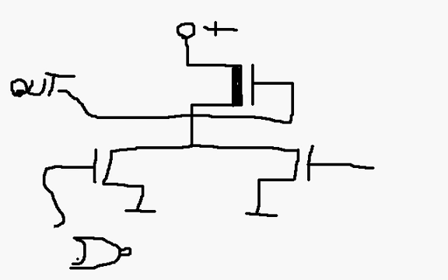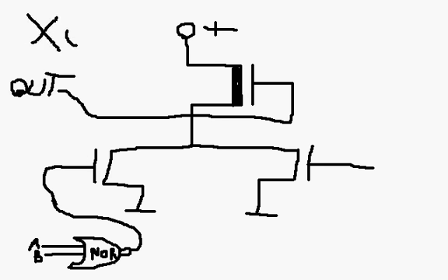And so what you end up doing with the NOR gate then is this NOR gate actually takes the inputs of A and B. So basically, inside the 6502, what actually happens is it borrows the output from its own NOR gates and pipes them into this side of its XOR gates. So this is one input into the XOR gate. I'll put XOR for exclusive OR up here, even though this isn't quite done.